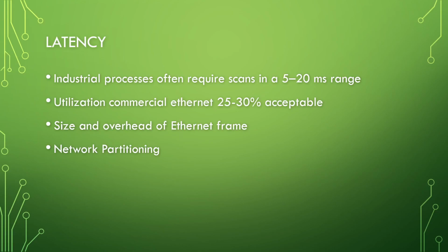A 5 millisecond scan time or latency requirement would be 200 times a second. Think about that. It's running its code 200 times a second. Or 20 milliseconds would be, what, 500? No, 50 times per second.